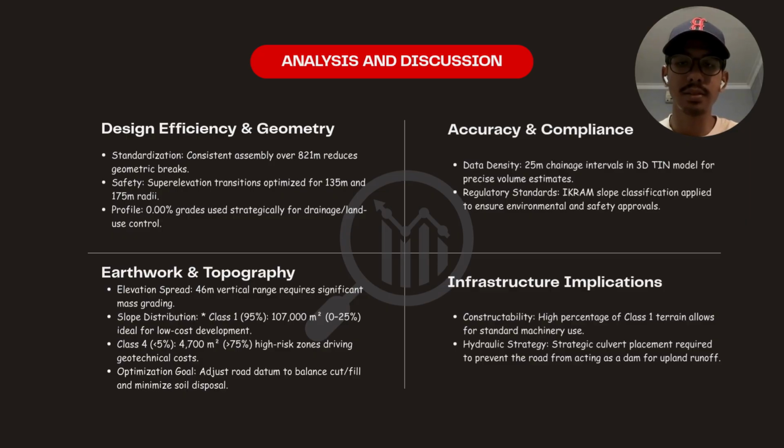Next is the earthwork challenge. The most critical takeaway from our analysis is the site verticality. We have a 46-meter elevation spread. Because our proposed road levels are currently set low, we are trending toward a cut-heavy operation. However, there is good news.